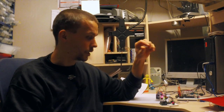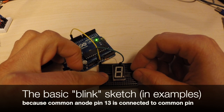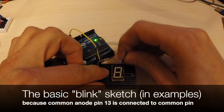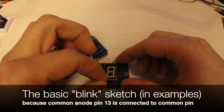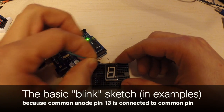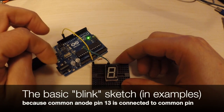But let's get right down to it and start with the most simple way of connecting a 7-segment LED display to your Arduino. First, to understand what a 7-segment LED display is, it's basically 7 LEDs bundled together to form a pattern that can make numbers. And you control these LEDs just like you would control any other LED. In this case, we're controlling it with the basic blink sketch. So you can see we can access all the LEDs by just blinking them.